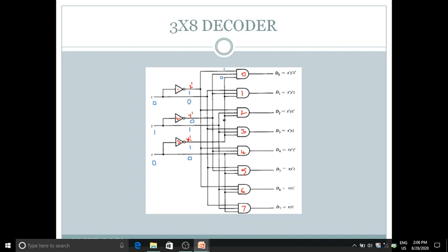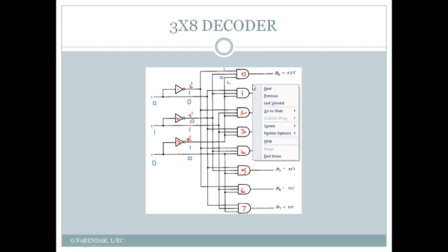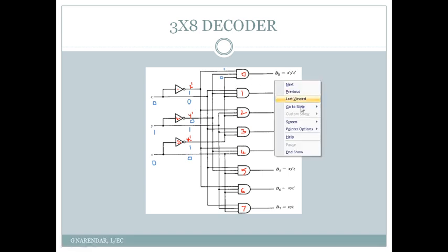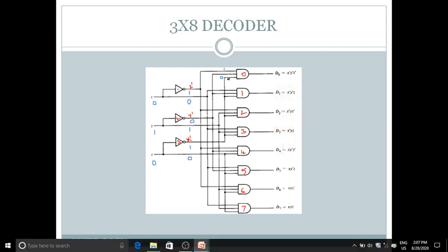It is x bar, with x equal to 0, so x bar equals 1. So x bar, the third input line, is equal to 1 for the 0th AND gate. We'll write the outputs later, after writing the inputs for all the remaining AND gates.